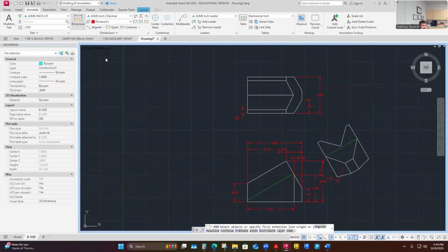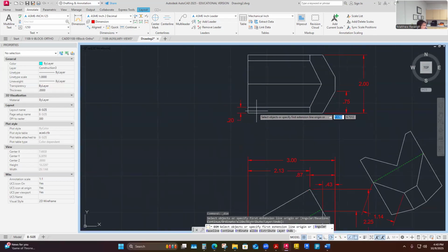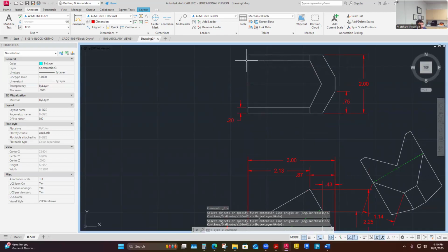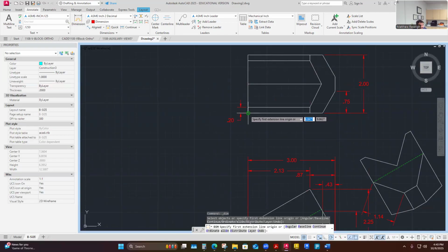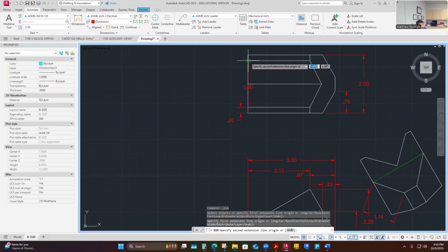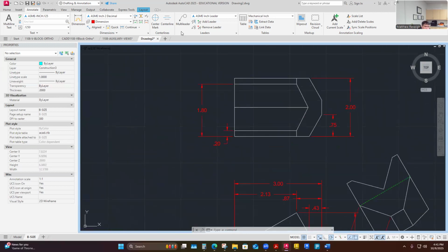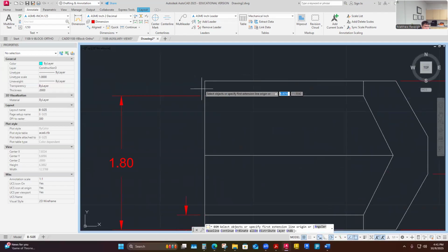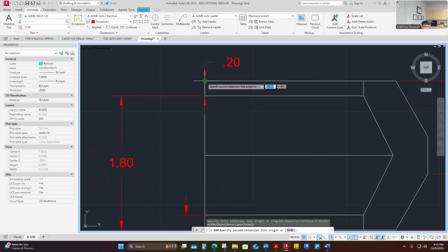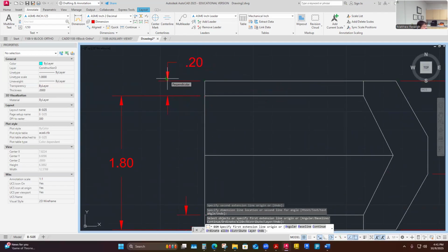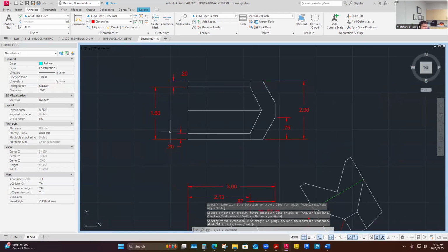Yeah, I think it is time to move on to the next surface, which is maybe this other surface that's like unto it. So that dimension would be from the front surface to this, which is maybe the preferred way to pull that rather than from the back over. I think it's still helpful to add this other dimension. I just think it may become a reference dimension, but it also takes a relationship with the part beyond what we have to know its functionality, to know which one is going to be, where am I controlling from?